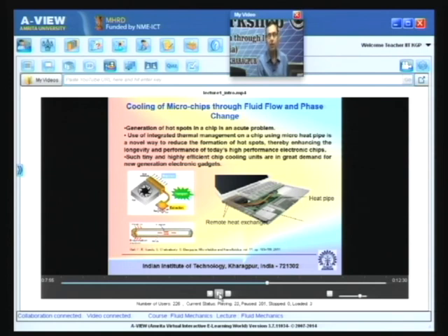The other strategy, which is again a futuristic strategy, is you can employ small droplets, and you can take a droplet from a location to a hot spot, and the droplet can take the heat, and the droplet can get evaporated. So, you can use droplet based fluidics, and you can control the movement of the droplet by a logic. So, it is fluid mechanics interfaced with computer science and automation, so that you can automate the motion of a droplet to move the droplet from one place to another place, so that the droplet sits on the hot spot and allows it for cooling.